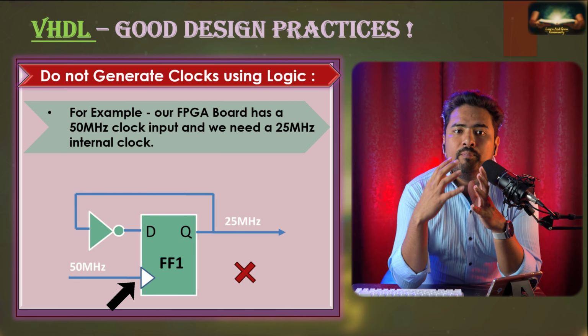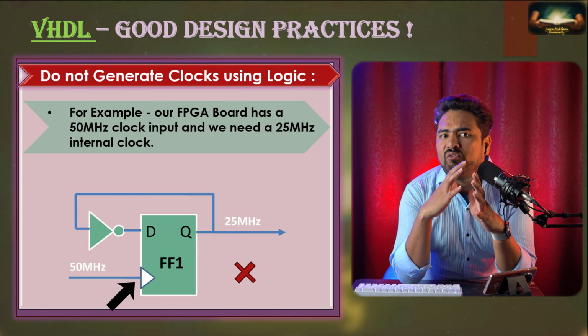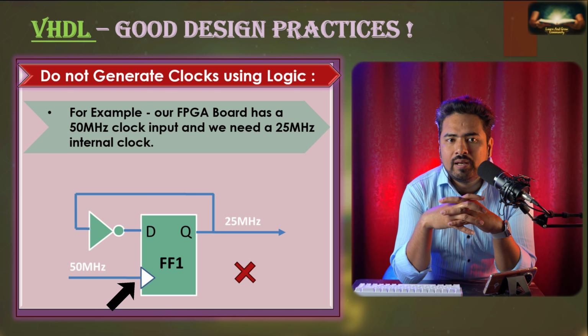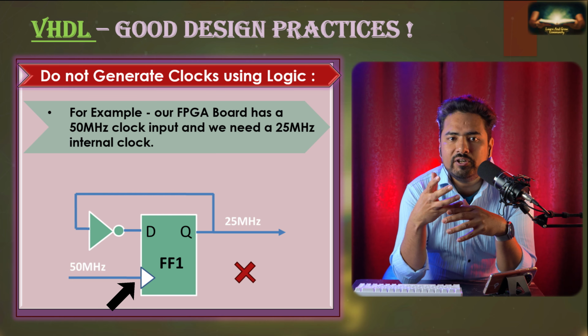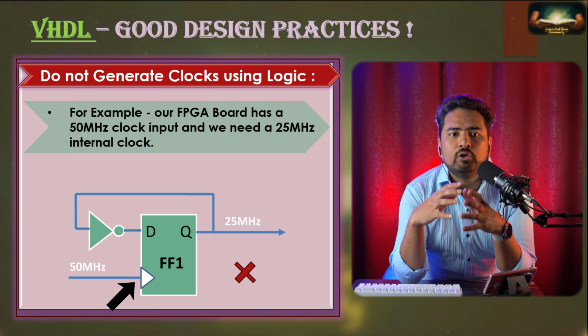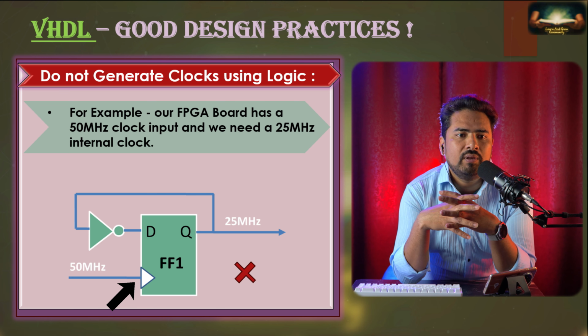Now, the clock is one of the important parts in FPGA designs, and is widely used in digital systems as well. In most designs, it is an external element, coming from oscillators, clock drivers, or clock generators, meaning some other external component. But the problem is that these components generally come with a fixed frequency, and your needs might be different for different projects. In such cases, we adjust the clock based on our project needs, and this can be done through your VHDL code.